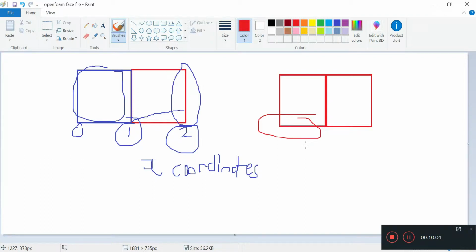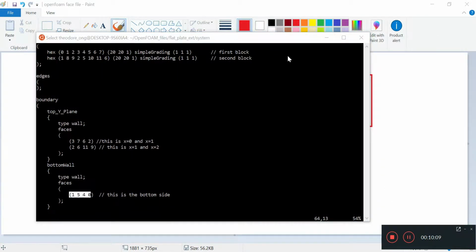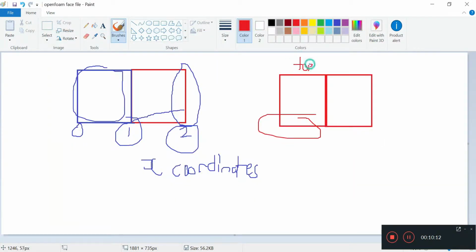non-moving wall. We want to call this, okay, the top, we call it the top y plane, with underscores and capital letters. This one we want to call zero gradients. Zero gradients. These are zero gradients planes. That's the boundary conditions we want. So it's here and here.